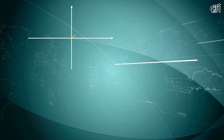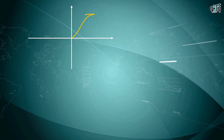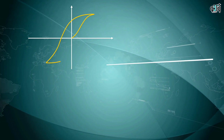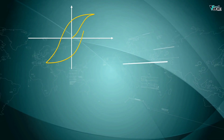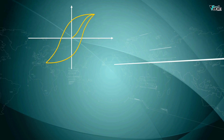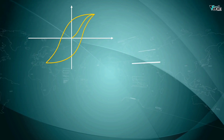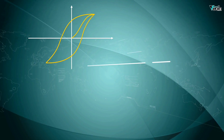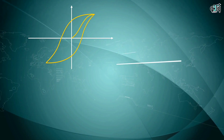Hysteresis losses occur in the core due to the residual magnetism. This means that the passing of the magnetic flux through the metal core in a direction causes the core to be magnetized and turn into a weak magnet. So in the next half cycle, a small amount of energy is lost to remove the magnetic effect of the previous half cycle, and it is constantly repeated.